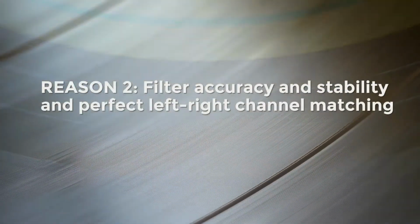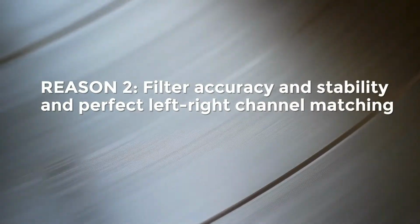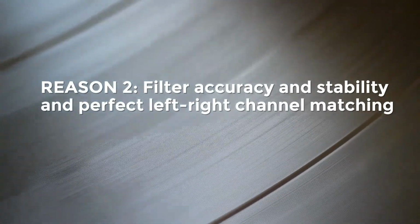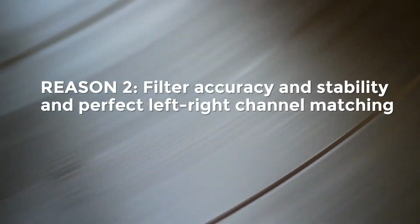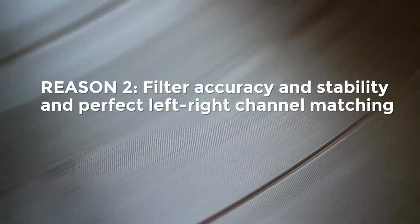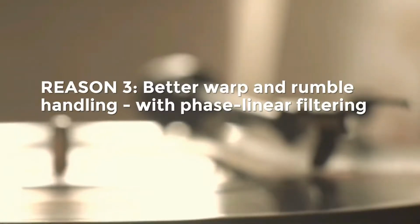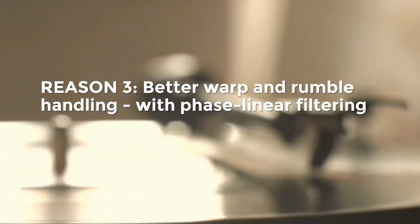Even the very best analog components can only be manufactured with a certain degree of accuracy, and that's really no better than 1%. And physical components are also subject to aging, such that they go off value, whereas digital processing ensures perfect channel balance and frequency response forever. LPs don't exist in a perfect world, so when warp and rumble are inevitably present, they need to be eliminated. And the rumble filter in Stereolab is a phase linear non-causal design, which means there's no phase distortion introduced.